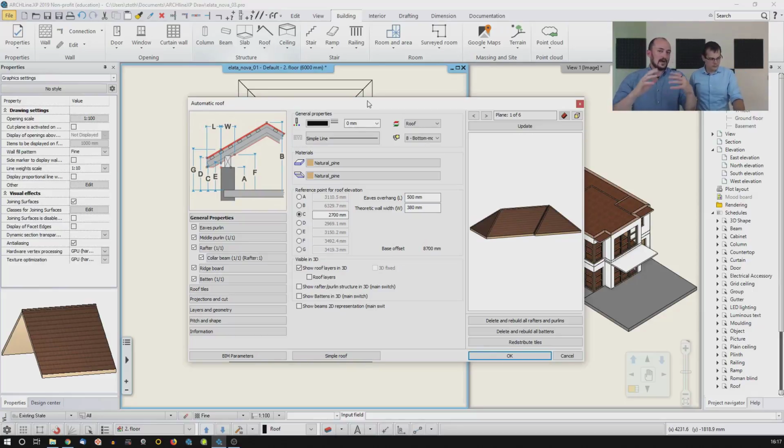I need to fine tune, for example, the height of this roof. If I would use this height, it would float above this area. So I need to change this C value, which I know of the design, to something else. Minus 300 would be the correct value, minus 300, according to these plans anyway. If you cannot find it at first, you can later change it in the 3D snap it, just as we did with the railing. But in this specific scenario, in this tutorial, we use minus 300.